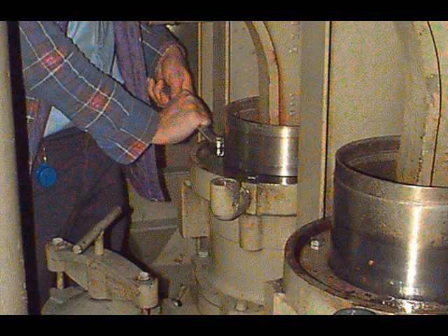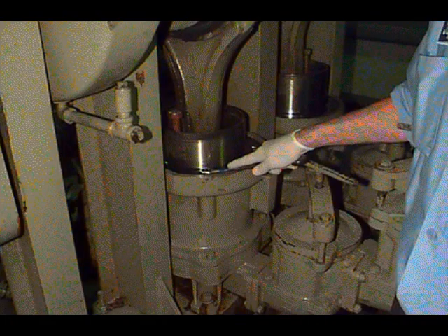As packing becomes worn, there will be excessive leakage of sludge or water around the plunger. Normally, this can be compensated for by tightening the packing gland to maintain only a slight amount of leakage. However, when there is no further take-up available in the gland, the packing will have to be replaced. Refer to the manufacturer's instructions and to the information in the previous section on replacing packing in a centrifugal pump. The procedure is very similar for plunger pumps.